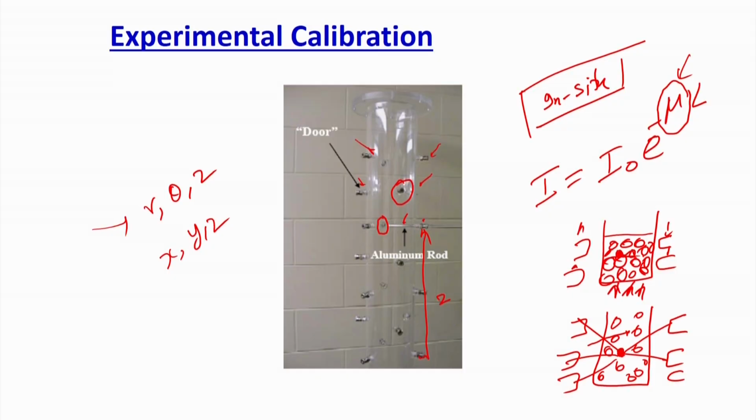While discussing the experimental calibration method, what we have said is that we have to put the particle at several known locations to create a lookup table in which we know that for a particular position, how much count will be recorded on each detector. Please note again that the calibration should be performed at in situ conditions, so that the distribution of the phases should remain the same.